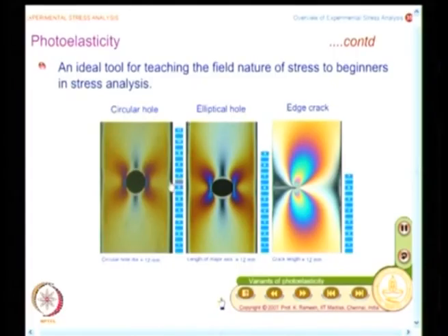You may wonder, I have an elliptical hole, and all these cases are finite geometry; I have a finite width and I have a circular hole. Analytically what I could do is consider an infinite plate with a very small circular hole, and here I will use polar coordinates to specify the boundary condition on the inner surface. When I go to an elliptical hole, you have elliptic coordinates to specify the boundary condition on the inner surface. At infinity you could consider it as a large ellipse, or a large circle; that is the way you can approach the solution.